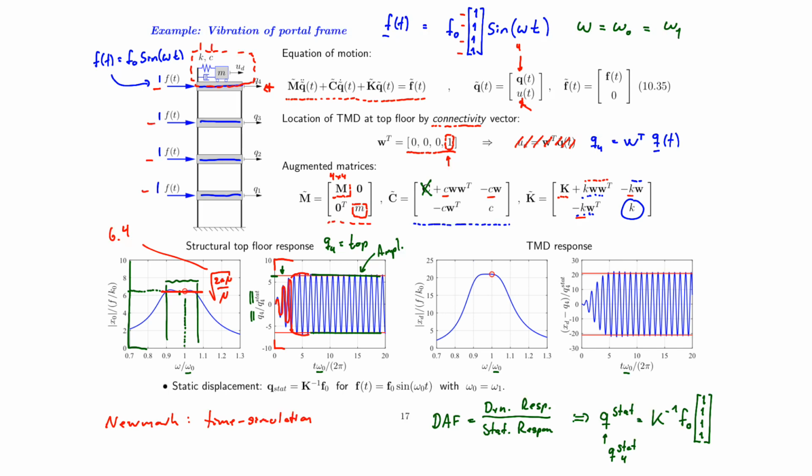So in the third figure, I have my amplitude of XD with the fully flat plateau around my resonance frequency, and you can see we are at an amplitude slightly above 20. And we remember that the amplitude level, and there wasn't a square root, that's quite important, is 1 plus mu divided by mu, and in our case that's 21.